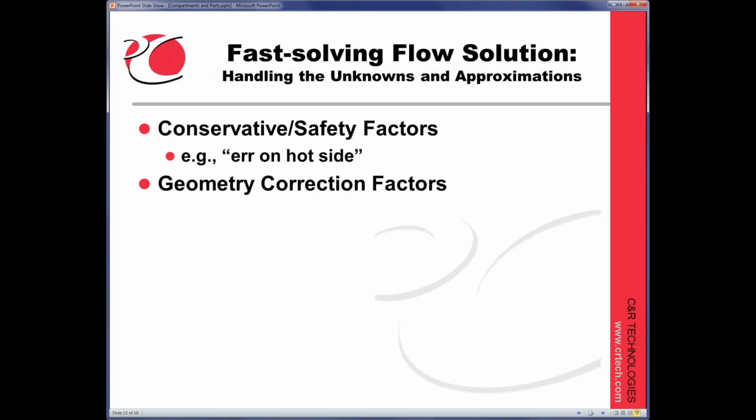And this is more for the natural convection or single phase convection sort of things. When you're dealing with boiling and condensation, it doesn't care as much about where you are. It just really cares about the local wall state. So that's fortunate. But if you are doing natural convection, and that would be true in a lot of the non-volatile fluid tanks, then it's important to know where you are in that tank and is a single convection factor really adequate.